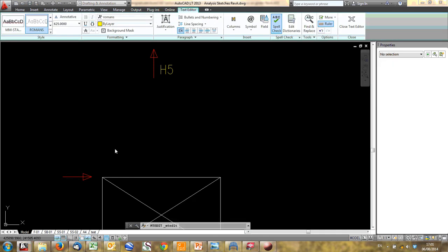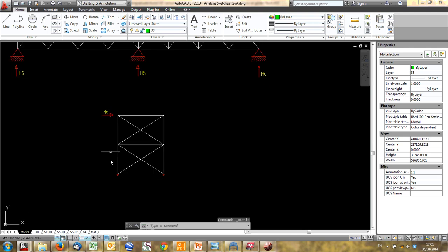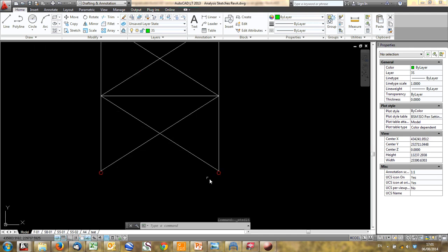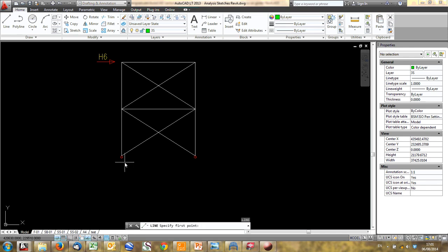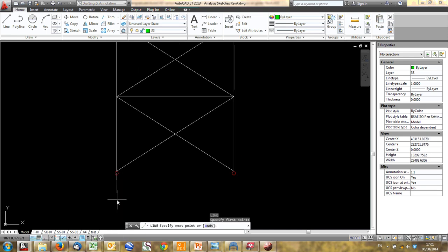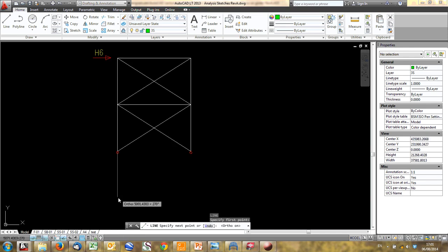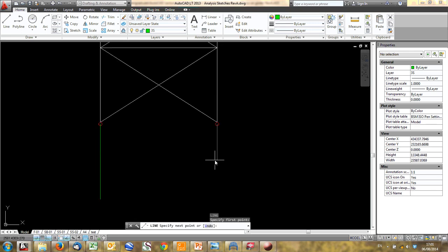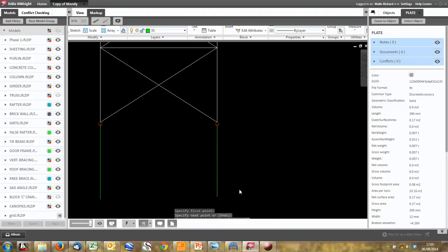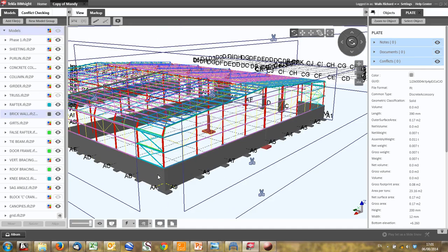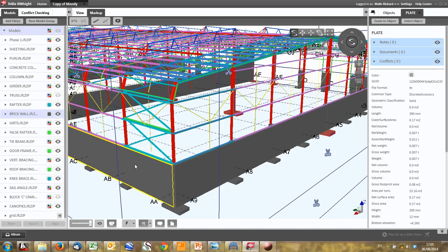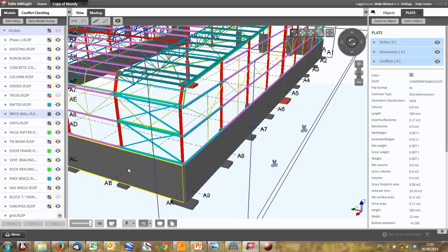And we've almost got our force all the way to the ground. I've just modeled the steel part at the top and made sure these are pins here, but you could add the columns below as well. Why we haven't modeled these, or why we support them here, is the brickwork is very stiff. If you fix the brickwork to the concrete with hoop irons or whatever, this brickwork actually stabilizes your structure, so you don't necessarily need to brace below it unless you have very high loads.